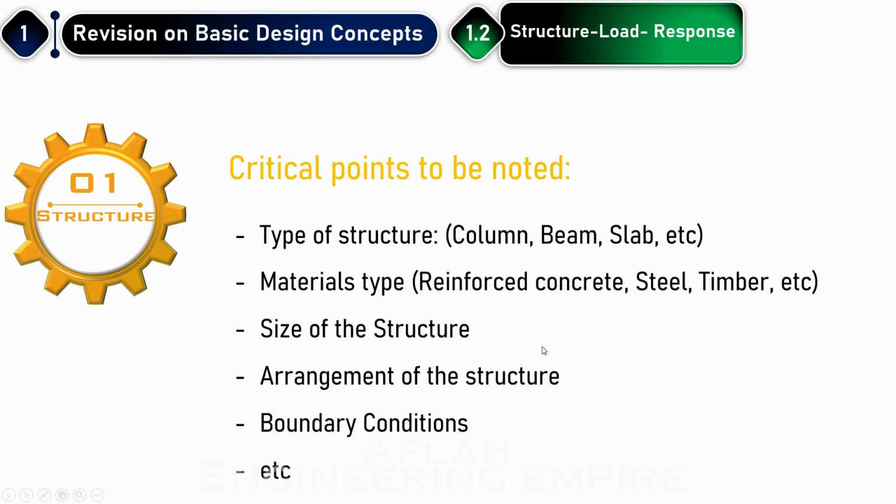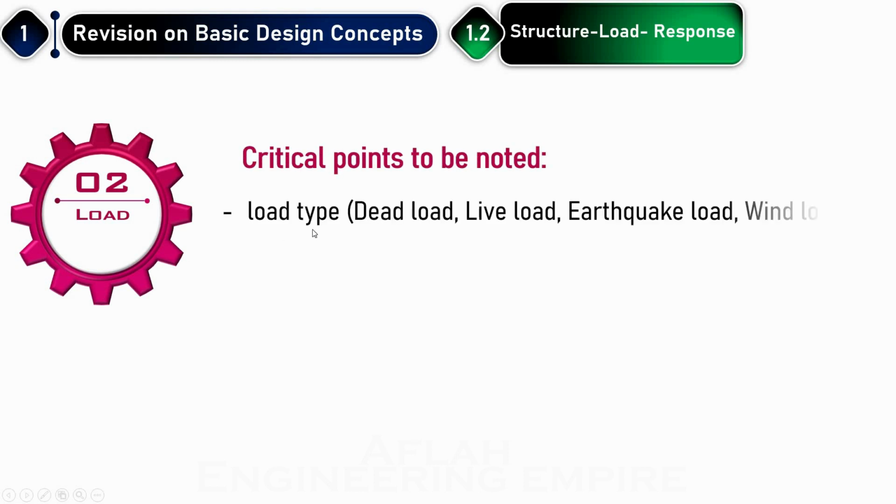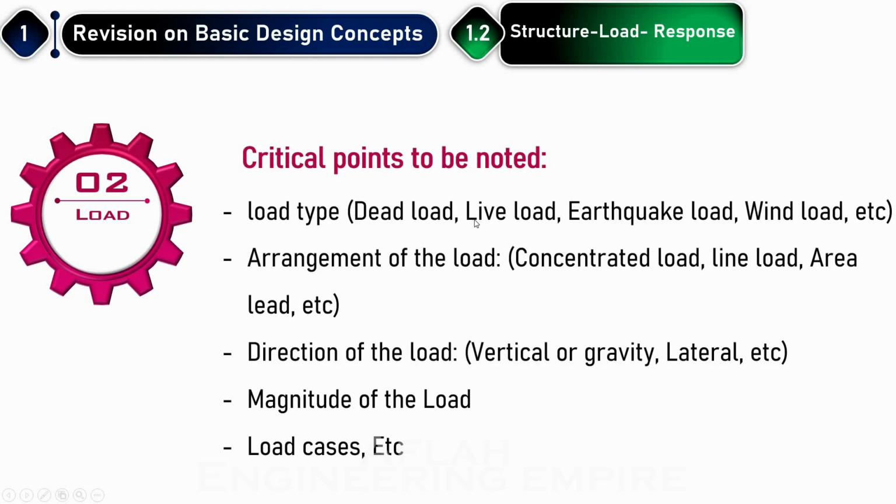There's a load. So in the load, these load types, is it dead load, live load, and so on. Knowing whether it is dead load or live load or earthquake will also affect the factor of safety that are related with these types of loads. For example, the dead load may be associated with 1.35 for the dead load, maybe live load 1.5.